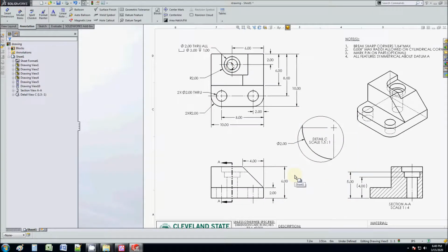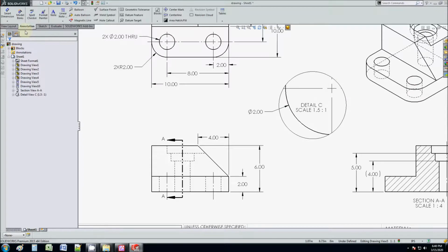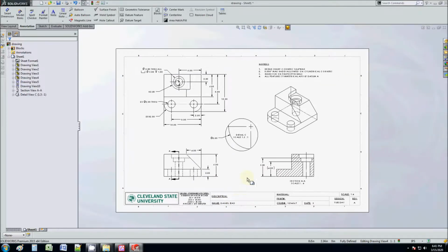And then finally, there's the chamfer dimension tool, which is shown here. It's just a way to save dimensioning on some of these. You just have to pick a line, and it's kind of cool. In just one dimension, you communicate this whole chamfer. See, it says the size is 4 by 45 degrees. So that's a nice way to save some space for dimensioning a chamfer.